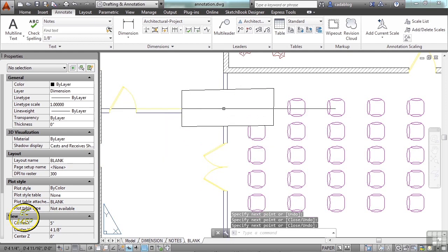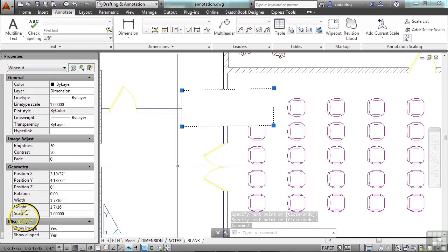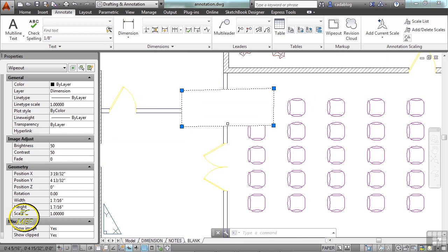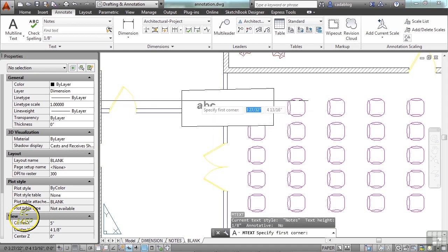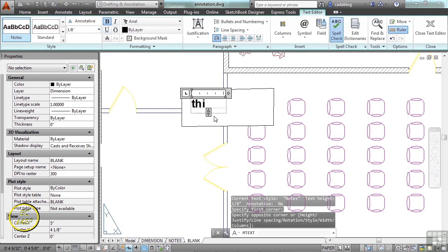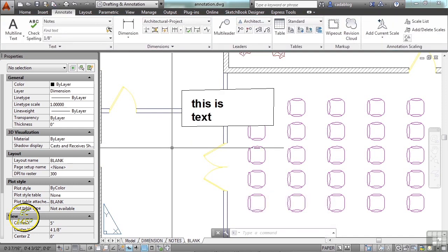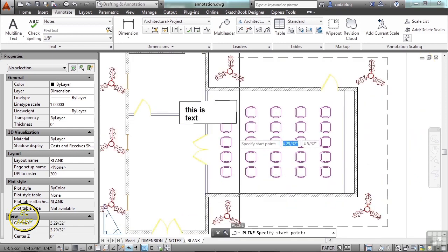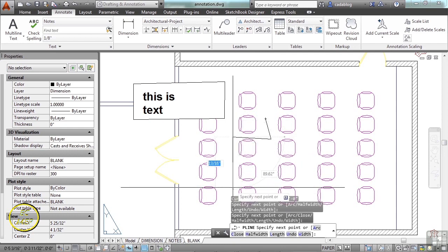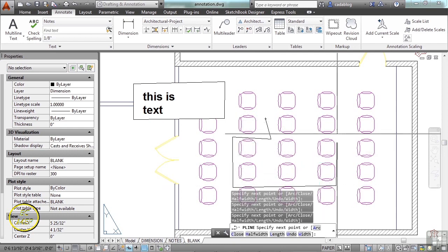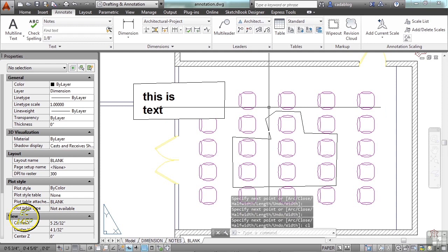And there you go. It's its own object. You can see it here in the Properties tool palette. And essentially, it creates an object that blocks everything behind it. So now I can put in text, or whatever I need to. If you have a closed polygon of any shape, could be a polyline, you can convert it to a wipeout frame.